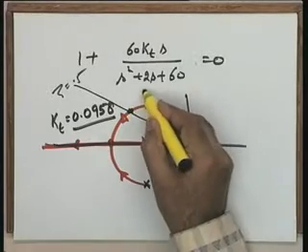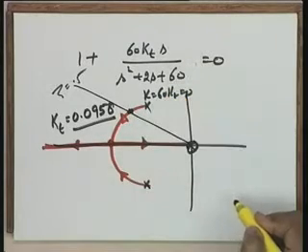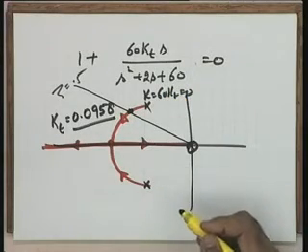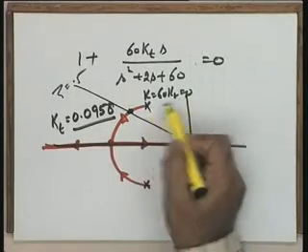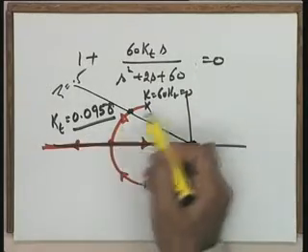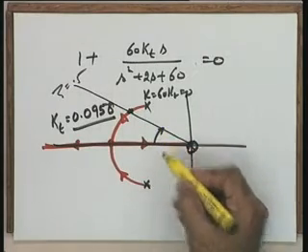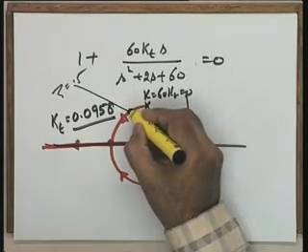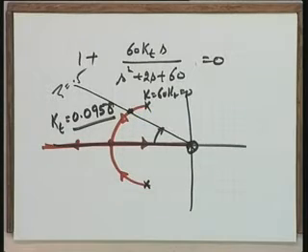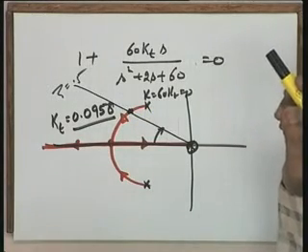Remember that the K parameter is 60 Kt and not Kt. You have to calculate Kt. The root locus gain in this particular case is 60 Kt. The value of Ka is 60 and Kt can be calculated from this. So, corresponding to zeta equal to 0.5, you can take this angle as cos inverse zeta, you can take this point, and from this particular point you can calculate the value of K and hence Kt. So, this design has been made.